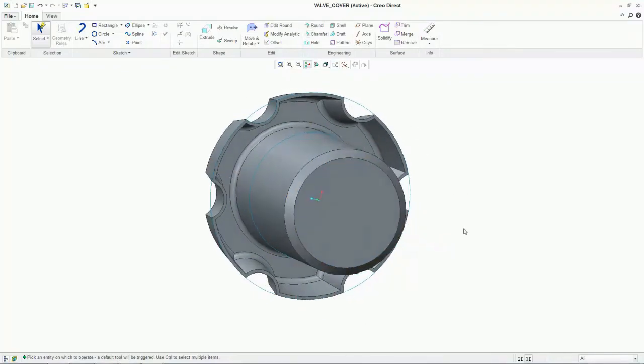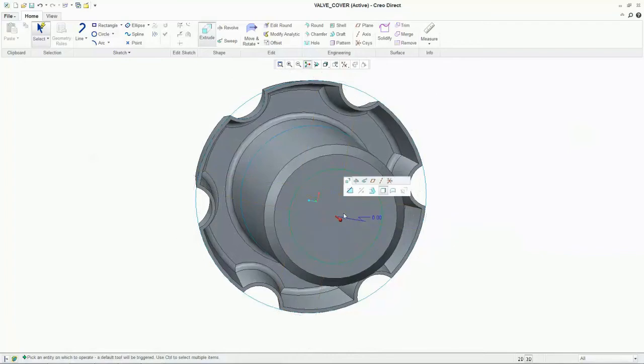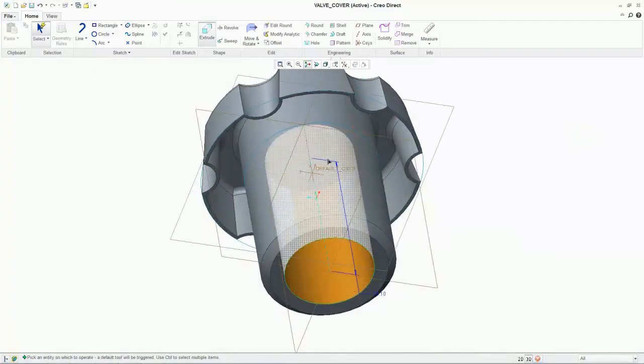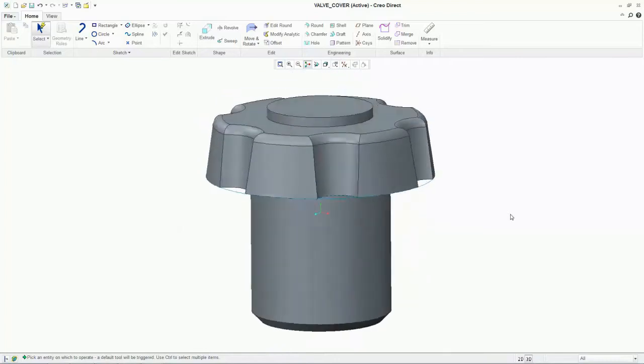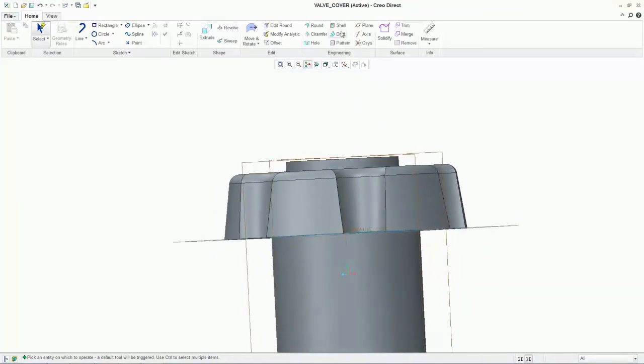In opposite order, selecting the surface, then the sketching operation, still brings us into 2D view, with which we will quickly sketch a circle equal to the size of the opening we desire. We'll extrude up into the stem, creating the hollowed feature. Each step being exhibited involves minimum mouse clicks, since most operations are either automatic upon clicking, or will become so once the desired operation is selected.